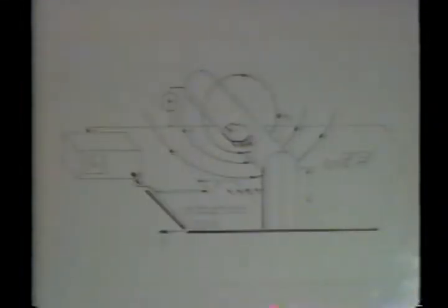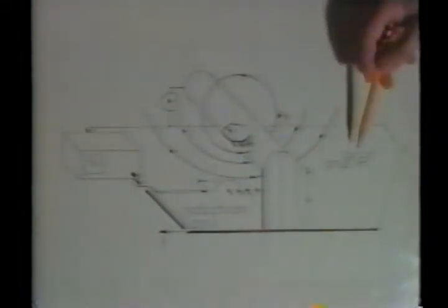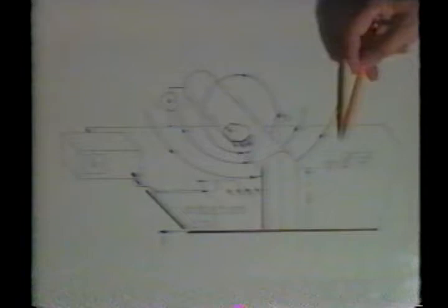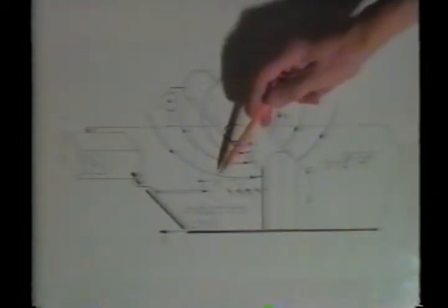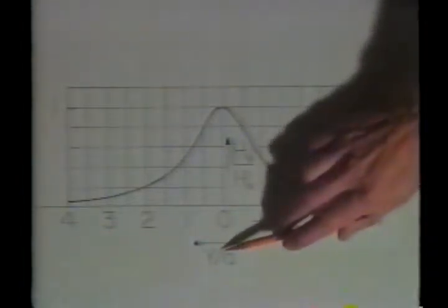This is the predicted distribution of normalized magnetic field with normalized probe position. H0 is the magnetic field at y equals 0. The tangential magnetic field is largest directly under the conductor, trailing off to 0 as the probe is pulled away. As the sensing coil is moved out from under the conductor, the tangential flux density decreases. Because there is little normal flux density just above the sheet, there is little of either of the components of magnetic field below the sheet.